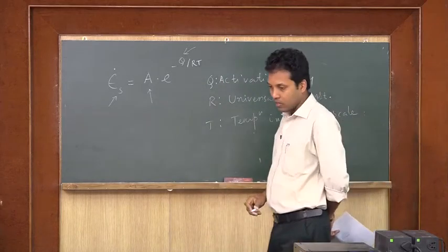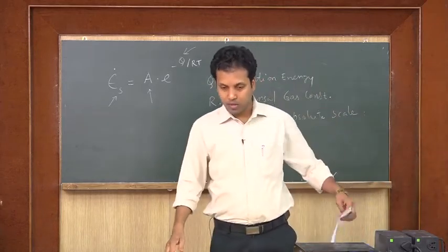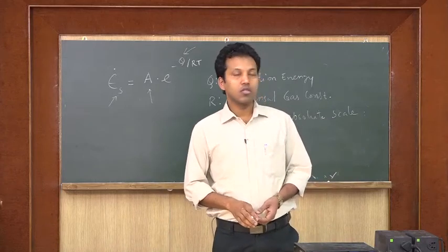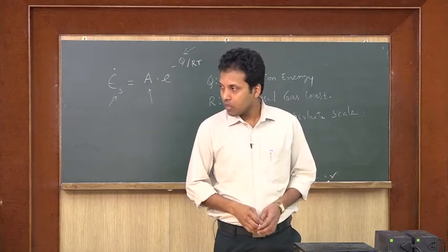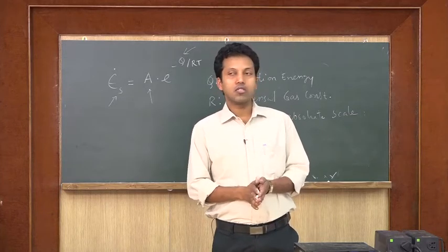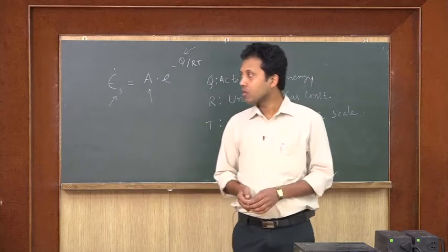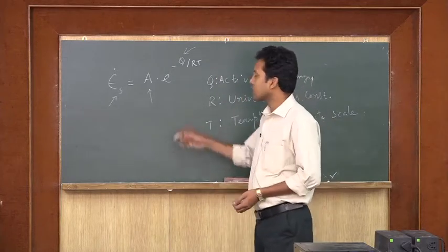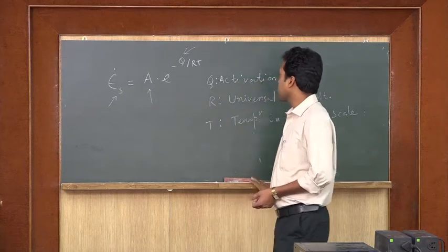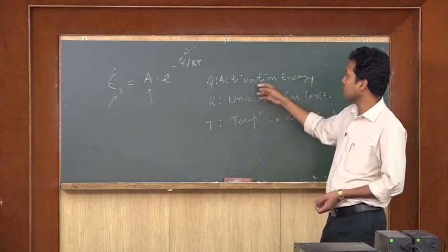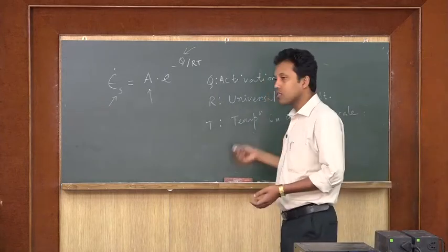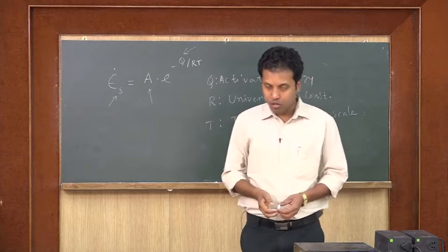so we understand that during creep behavior atomic diffusion takes place inside the material. So, it is a temperature assisted phenomenon and there is a rate associated to this. So, this is a deformation rate type equation where Q is the activation energy, R is the universal gas constant and T is the temperature, we know that is in absolute scale.